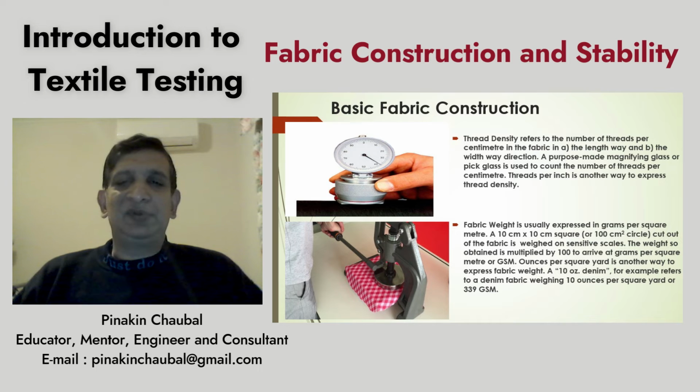Fabric weight is usually expressed in grams per square meter. A 100 square centimeter circle or 10 by 10 centimeter square cut out of the fabric is weighed on sensitive scales. The weight so obtained is multiplied by 100 to arrive at grams per square meter or GSM. Ounces per square yard is another way to express fabric weight. A 10-ounce denim, for example, refers to a denim fabric weighing 10 ounces per square yard or 339 grams per square meter.